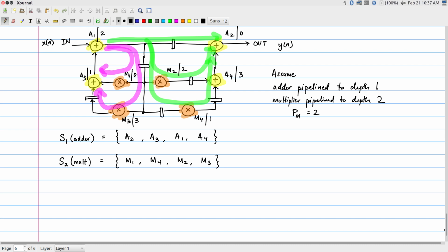There are these junction points where something splits off into two, while mergers are of course indicated by additions. The splitting off into two is a clean way of drawing it as far as the block diagram is concerned, but as far as the data flow graph is concerned, that's hiding some information, because those junction points are not really separate nodes in the data flow graph.